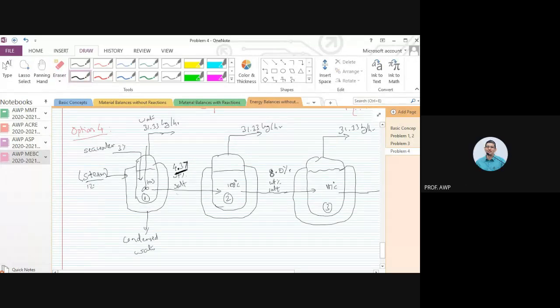Correspondingly, pressure will be lower. I have the steam table open with me. If we look at 123, steam pressure would just be 2.1 bar. To that extent, latent heat can be more.